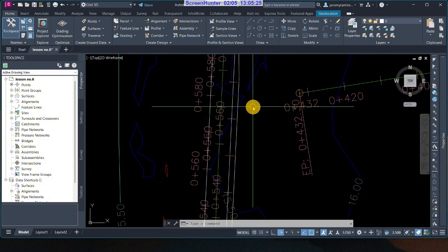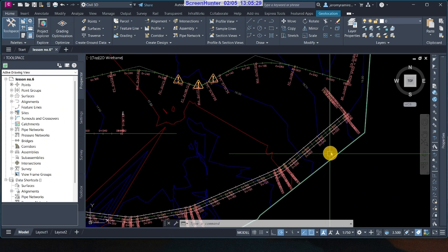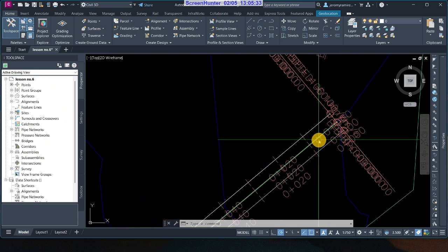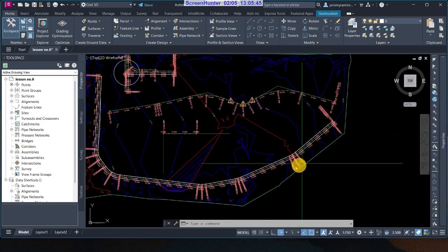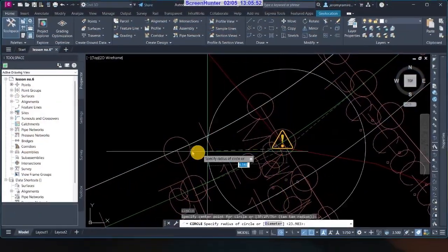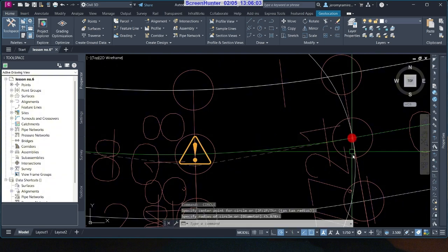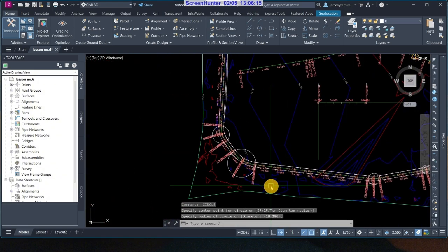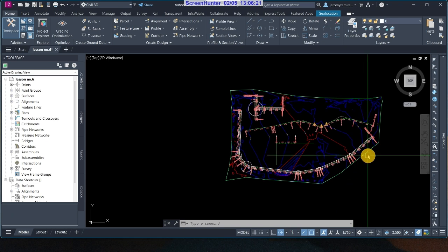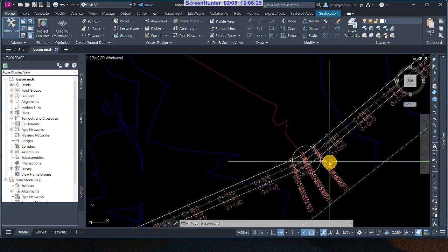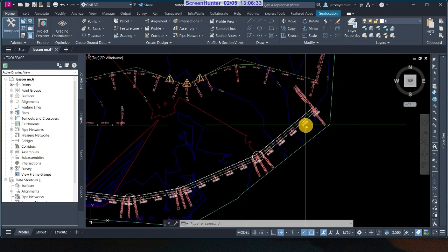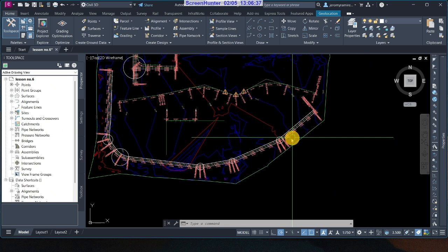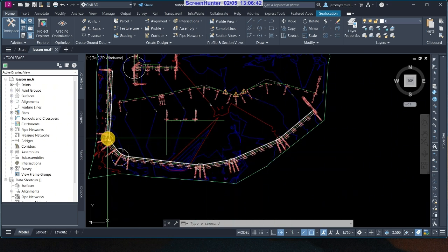Now let's go to the basic design parameters. As I said a while ago, we use the 60 kilometers per hour design speed for all of this road length, from the start to the end. We use 60 kph. It is critical if we use 60 kilometers per hour speed. So for example, if we use 40 kilometers per hour in our code, we're going to change our design parameters. We have 1, 2, 3, 4, 5 curves.